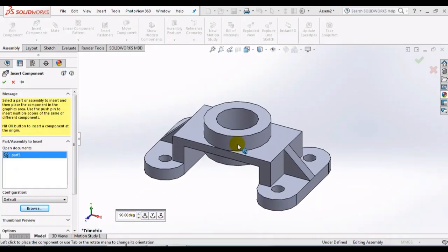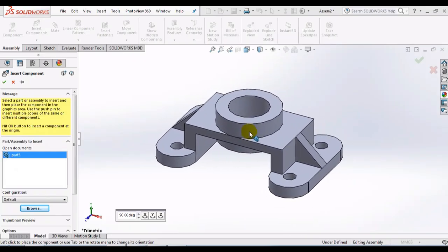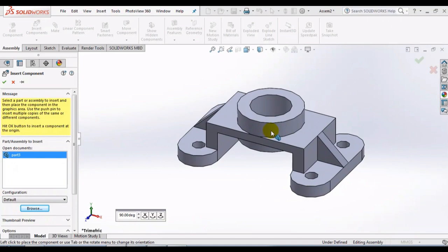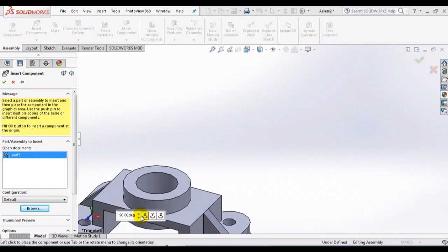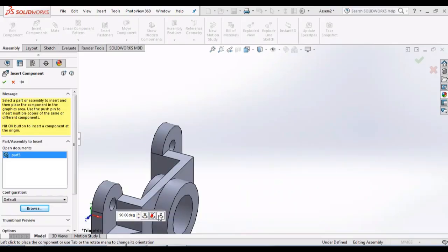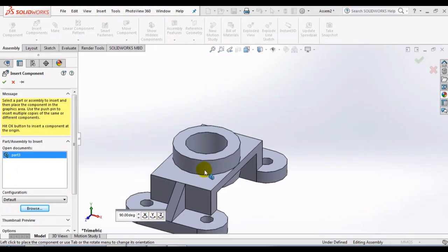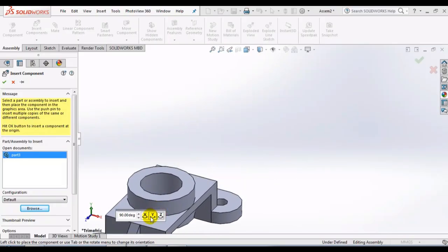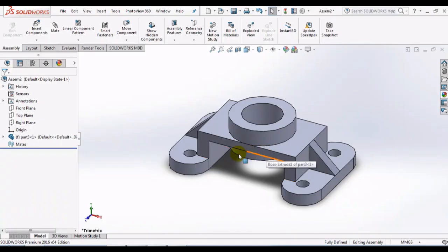If you want to set your part in the proper position, to make this plane properly horizontal, you need to make an arrangement: you can rotate here by X, Y, Z, and you can change the degrees and make a correction of positioning. Okay, so in our case it is like this. Once you click the left mouse button, that will set it onto your assembly.